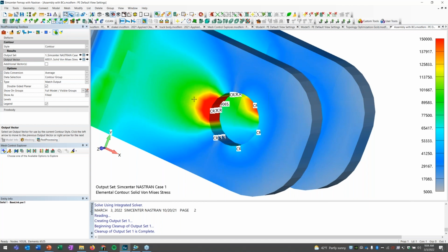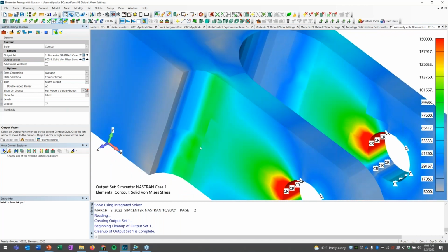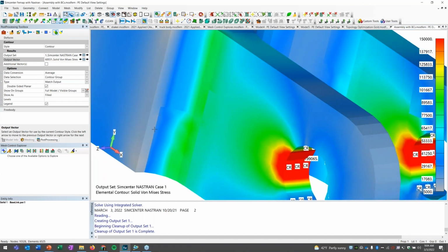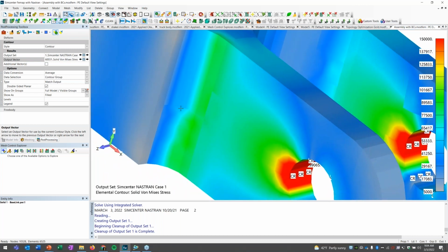Now, around here, we have a very smooth contour. It'd be hard to draw exactly where those element divisions are. But in this region here, it's a bit more obvious where we have these breaks. And those breaks are coming from the fact that we have parabolic and linear elements attached together. Femap recognizes those as the different types and doesn't automatically average stress results across those boundaries.